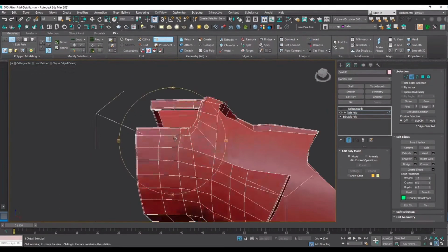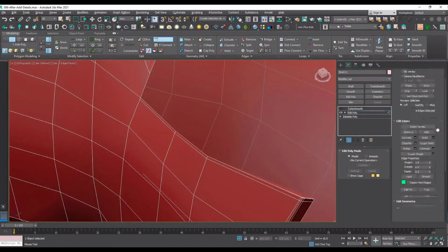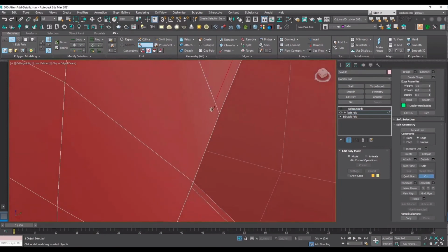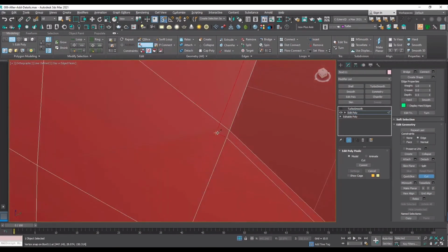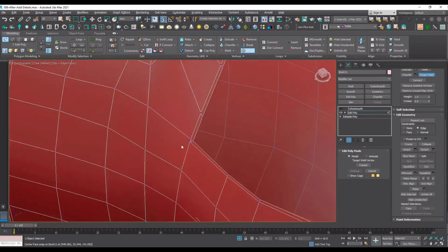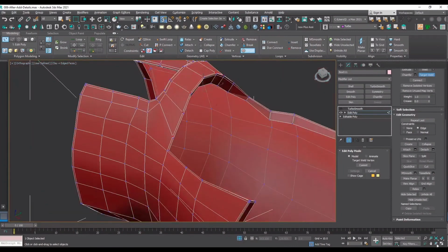So let's see what we got in this L looking shape here. We know what to do here. I add the edge loop and then pick up my cut command and then like this, and try to connect my edges to the other side. But here, as you might have guessed, I add the diagonal edge to maintain the curve because we want a curve after the turbo smooth, and just quickly using the target weld tool, I connect the vertices to each other.